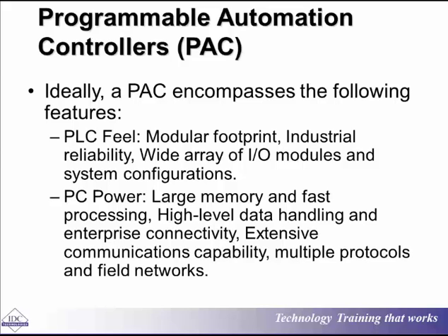So in summary, the PAC, or the Programmable Automation Controller, has a PLC footprint. In other words, it has the ability to take input-output, but it has a large memory compared to a normal PLC, high-level data handling capabilities, and very large communications or networking capabilities.